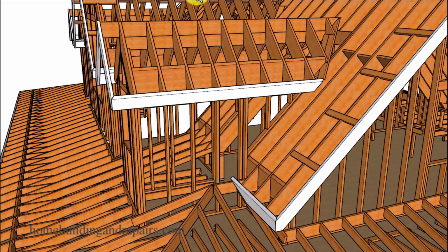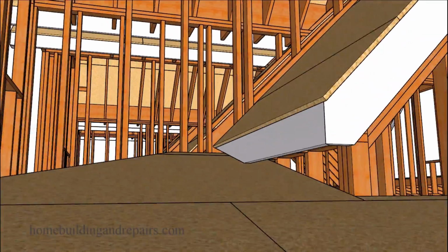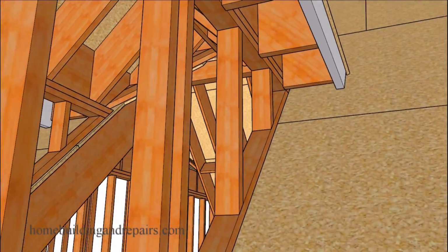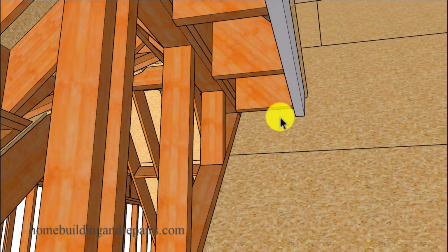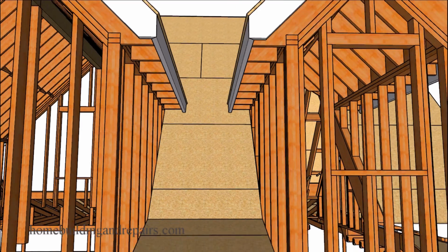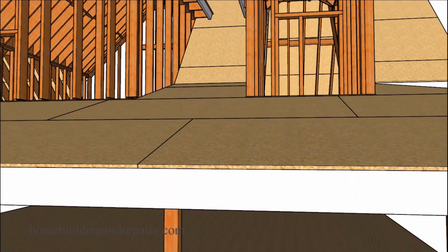Let's go ahead and add our fascia board and then zoom in on a couple of sections where the fascia board goes over the roof sheathing. You're going to need to have a gap here to allow for the roof shingles to slide underneath the fascia board. If you don't, the roofer won't be happy. And then a view of the corner here. You've got to make sure that wherever you need the roof shingles to go under, that you have enough space for them.